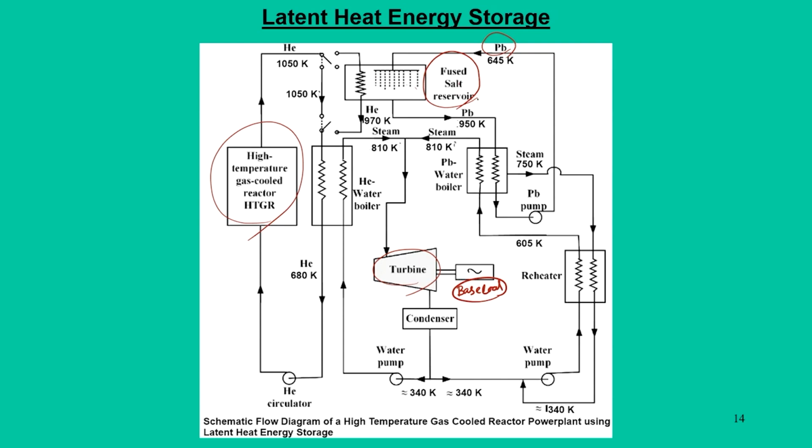So, thereby the fused salt gets the necessary heat, so that energy is stored here. Now, during the discharge period, this energy can be released to cater to the need for the peak heating hours. So, here the main plant operates with water as the primary working fluid, but other circuits involve materials like helium coolant.